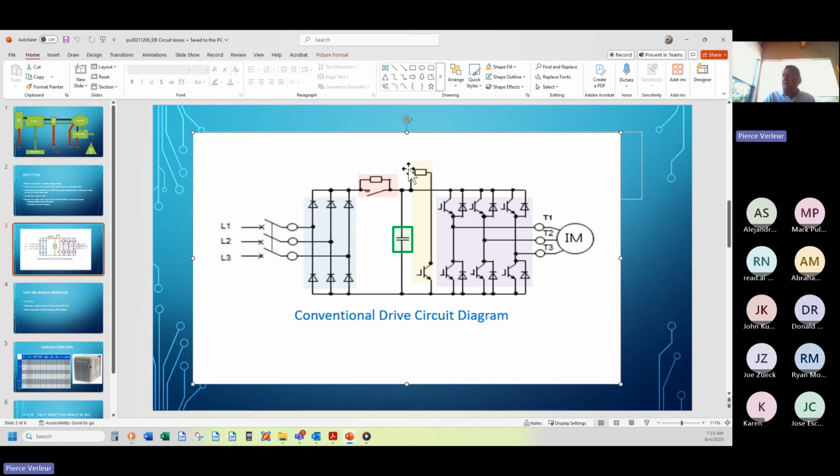And here is where I want to focus you, the yellow portion of this circuit. Initially, when the motor becomes an alternator and pushes power back, it's pushing AC back, as I said. So when you measure here at T1, T2, T3, it's AC. These 6 diodes, similar to these 6 diodes, take the AC from the motor and rectify it back to DC on this DC bus. This is the plus rail of the DC bus. This is the minus rail of the DC bus. Initially, these power capacitors, which had been drained a little bit because the motor was lifting the load, have a little room in them to absorb some of that energy coming back, but not a lot.